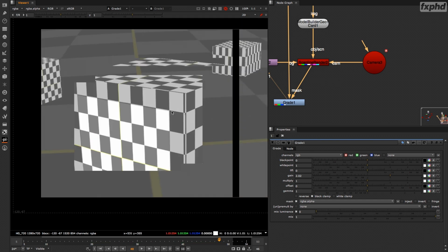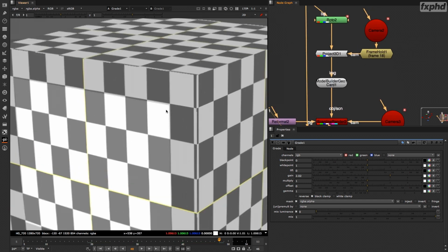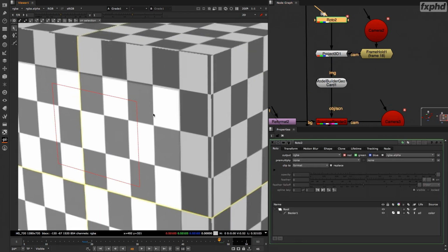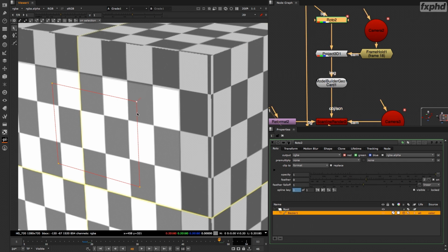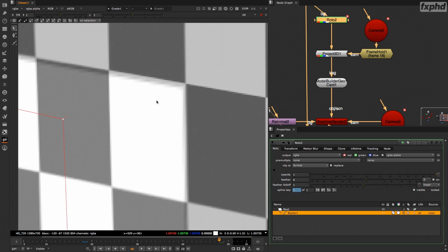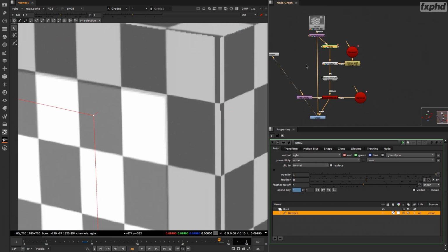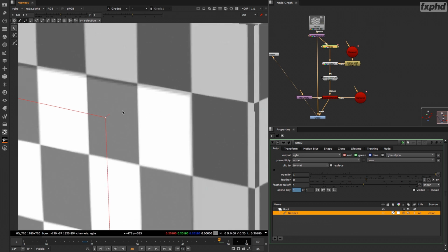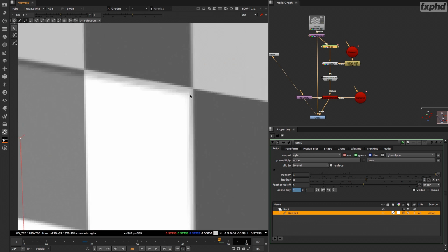So now if you want to adjust the roto shape, if we double click on the shape here, you see that we still have a UI problem, and that the shape, even though we can select it, is not aligning with the output of the scanline render. So that's one problem that I don't really like with this setup: if you need to do some tweaking, you'll have to select the point a bit off from where it should be landing.